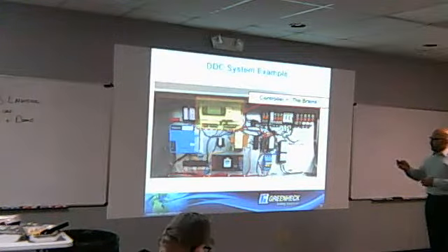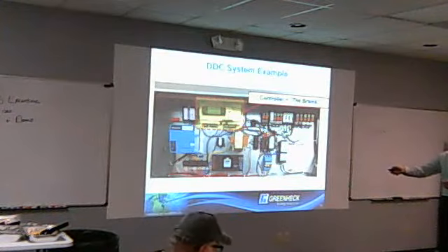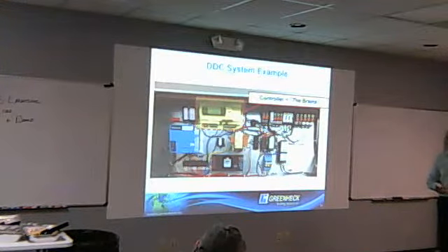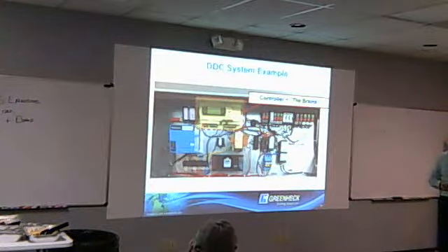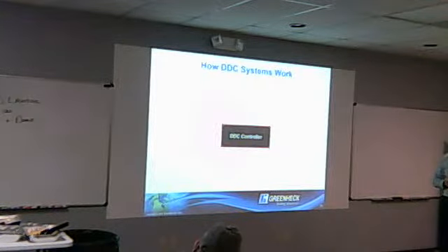So this is programmed with a number of different scenarios that can simply be turned on and off in the field. Usually somebody will tell us up front what it was, so it's programmed, but maybe there's a change and somebody says, oh, I don't want to do a time clock now, I want to do it on a temperature. So we can easily change that. So instead of thermostats, you've got all thermistors going back with AC control, doing pretty much the same thing. At the end of the day, it achieves the same thing, just a little different method of doing it.